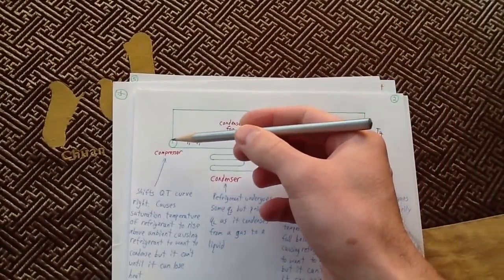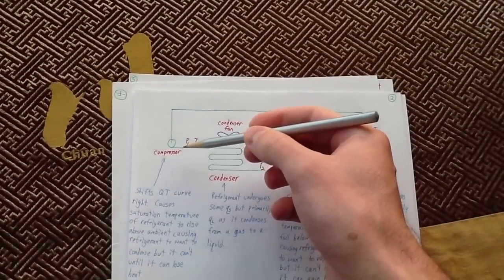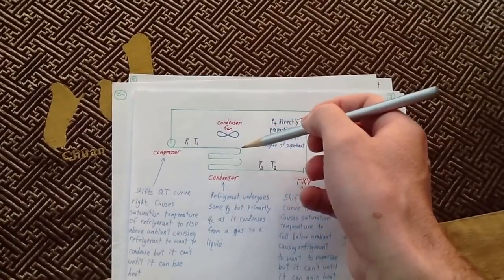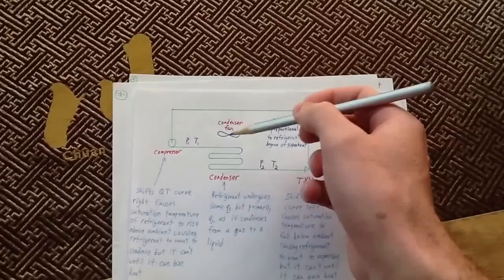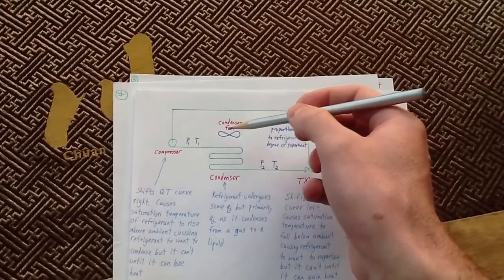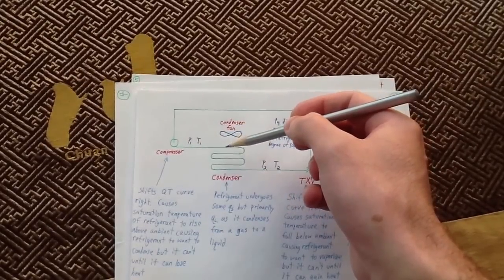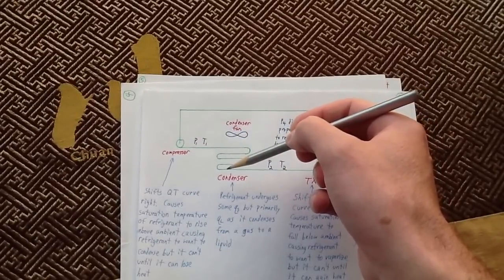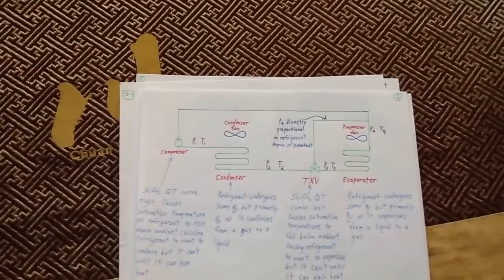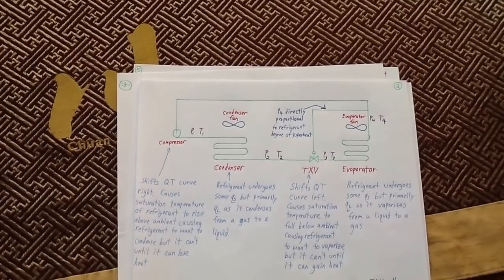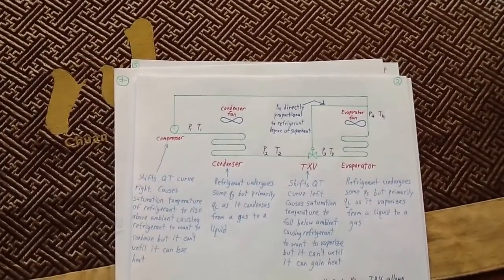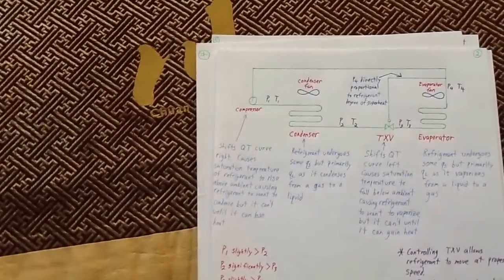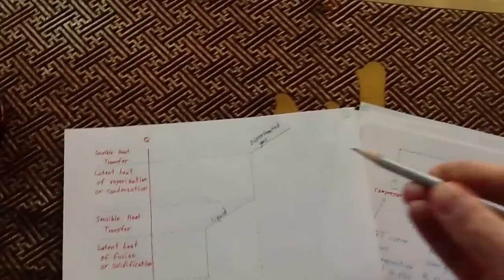So now you have gaseous refrigerant, fairly high pressure, fairly high temperature. It's then going to go through a component right here called the condenser. Because it's high temperature, the idea of the condenser is to blow air across it, and this cooling air cools off the refrigerant within the condenser, and then the refrigerant, as it cools off and you subtract heat away from it, it's going to go through this latent heat of condensation that we discussed right here.